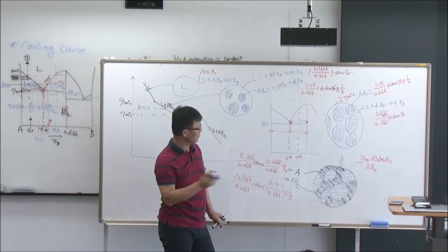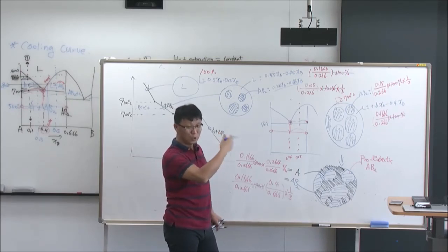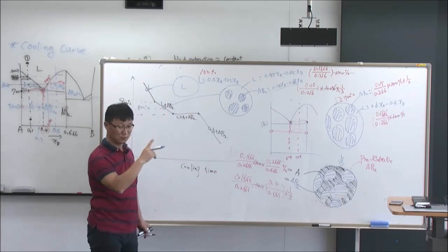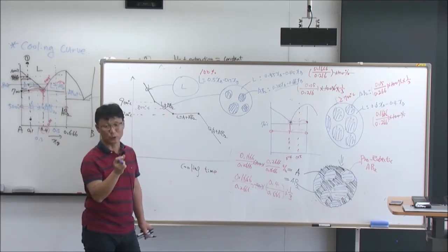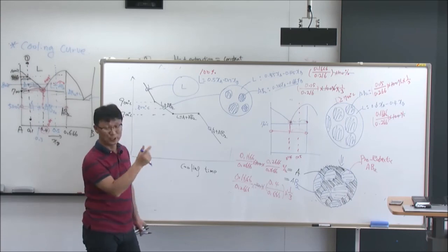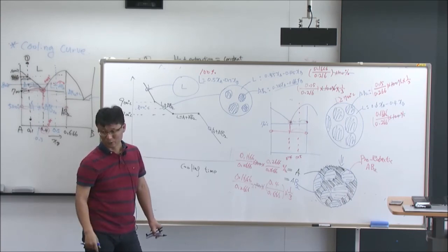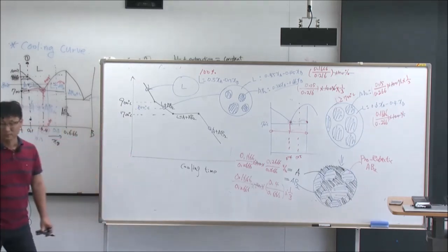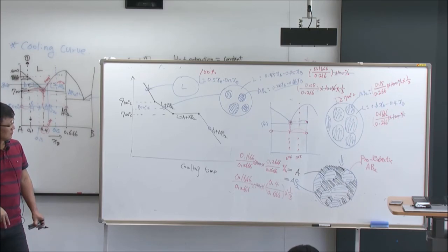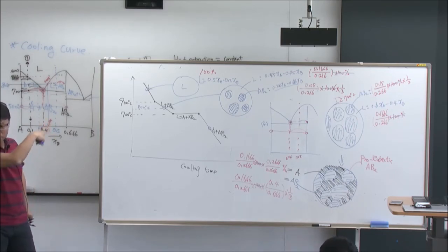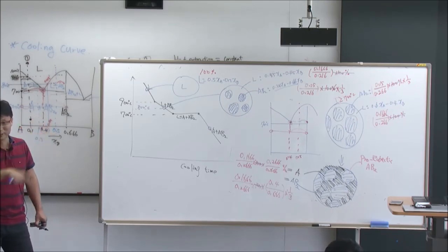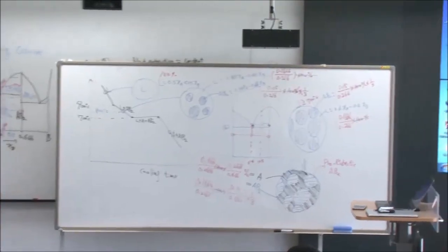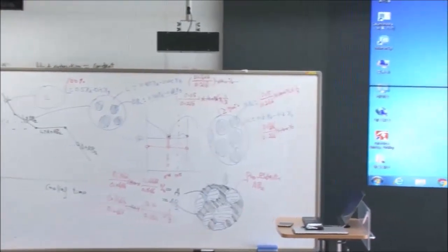So it's a bit complex because you have a molar phase diagram with some stoichiometric compound, and the stoichiometry is more than 1. So you have to make sure that you are not overestimating the amount of moles of each phase. Same thing for the previous one. Even there, you have to take out all this 100%. It's not mole percent of the entire phase. I'm sorry about that.